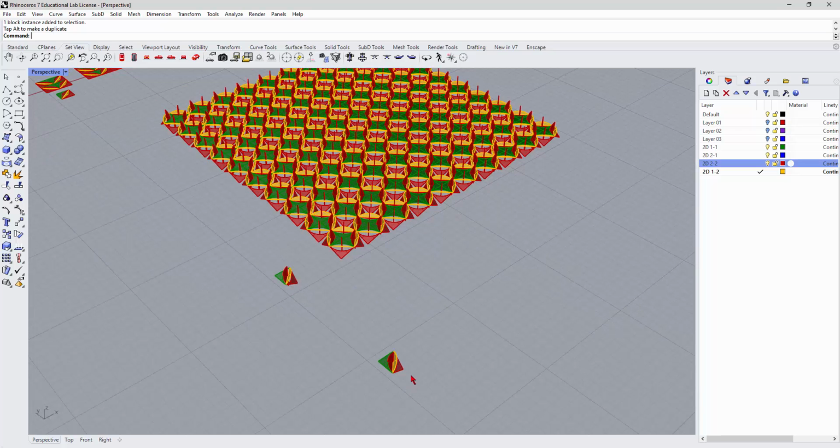That's very simple. You can come in and pick this guy and array it and just use the Z, right? So I'm just going to go to array. And then in the X direction, we'll do 10, that will be fine. In the Y direction, let's do 2. And then in the Z direction, let's do 10, right?